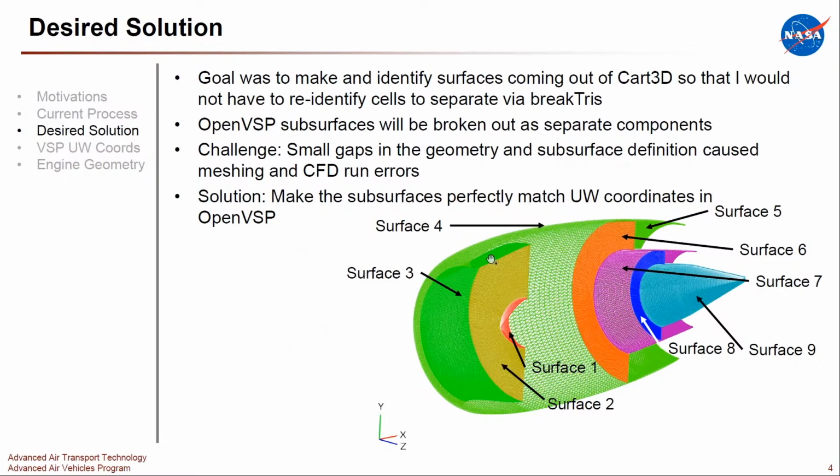This is an overview of what the model ended up looking like, where you have your spinner, your inlet. This inner surface here is actually a separate surface. So if you're doing your drag bookkeeping, the engine makers typically count this towards their ram drag, whereas the external nacelle drag gets booked up with the airframe typically. Same thing with the inner parts and so on and so forth.